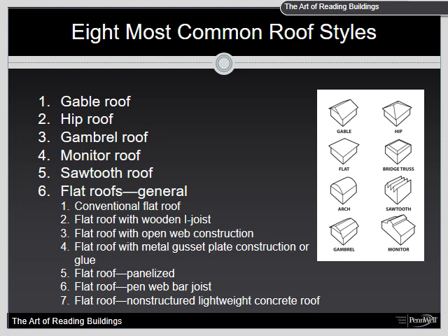Metal gusset plates or glued joists, when exposed to fire or high heat, will fail. In addition to the metal gusset plate, it is easy to visualize that if trusses are encountered that are glued together, and glue melts at a moderate temperature, collapse will also occur quickly. And of course, the sheeting of the smaller plywood or the OSB will burn and fail at a faster rate than traditional construction methods.